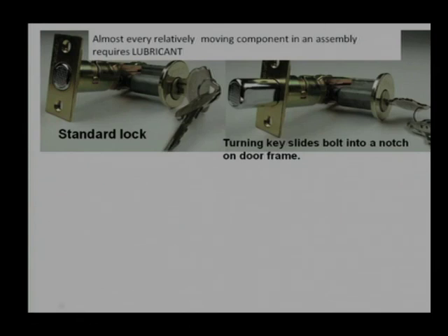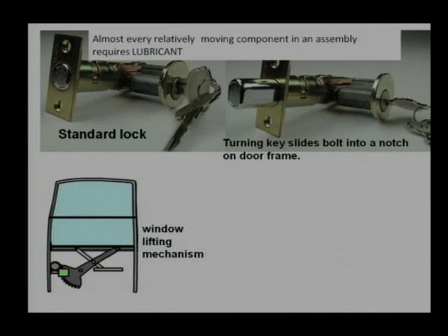Here we can find that if there is an on and off key, this bolt will be reciprocating. If there is a reciprocating motion, then friction will be there, and if we do not provide proper lubrication, a lubrication layer, or a proper coating on the surface, then there will be high friction and jamming will occur. It will not work satisfactorily for a longer time.